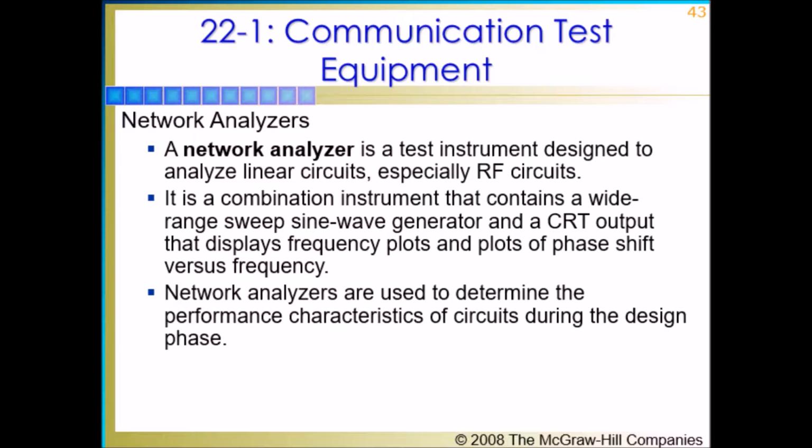Most vector signal generators are provided with pre-programmed signal formats for the most common wireless standards, while a vector signal analyzer is an instrument designed to capture and provide a way to disassemble a signal to see its detail. A vector signal analyzer is similar to a spectrum analyzer but with more output options. It is useful in design to ensure that new circuitry meets the desired standards. It is also useful in troubleshooting to locate problems and standards variations.